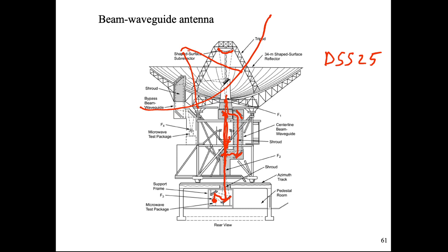So when there are elevation changes, all these mirrors have to change their angle, and it's impossible to have a straight line. You have to make sure that the optics is such that, pretty much like in a binocular, the RF signal reaches the feed whatever the elevation and azimuth are. So I hope you understood that with a straight waveguide, you can make observations only in one direction.